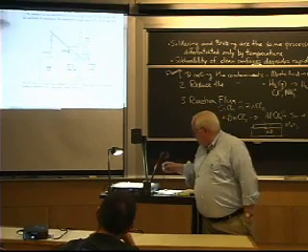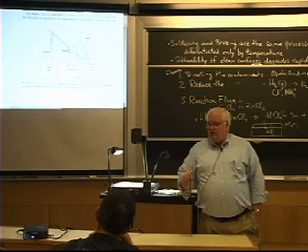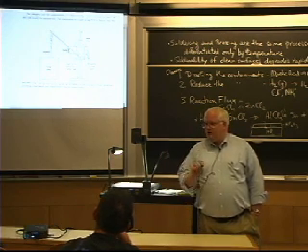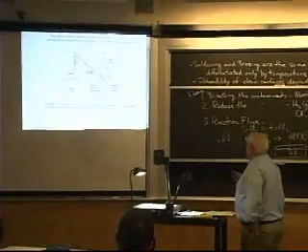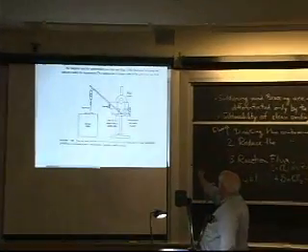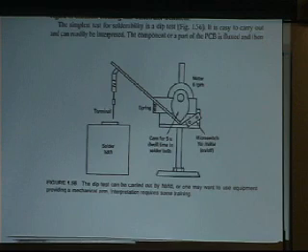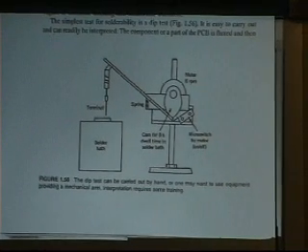They actually build machines that dip it for a given controlled amount of time, so you know exactly what's happening. They set the cam for a 5-second dwell time in the solder bath, so you're not relying on variability of human error in how long they do it. But that's one type of test.